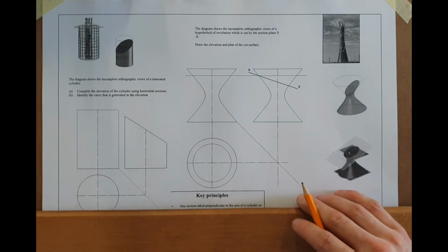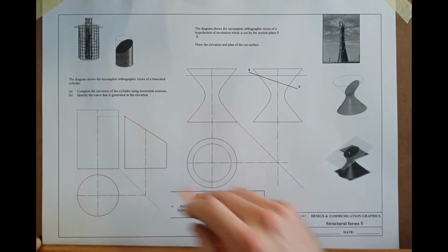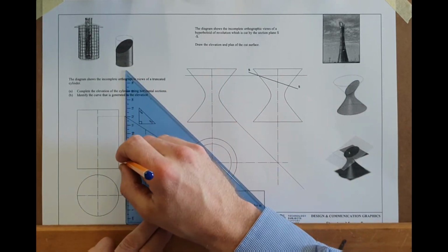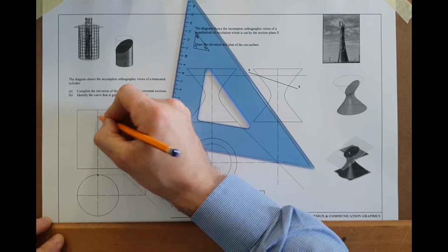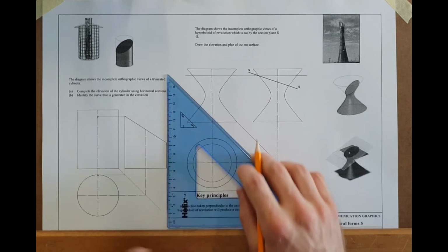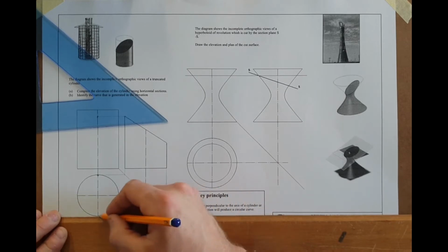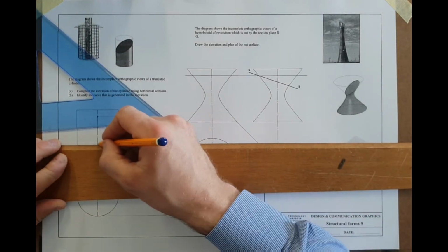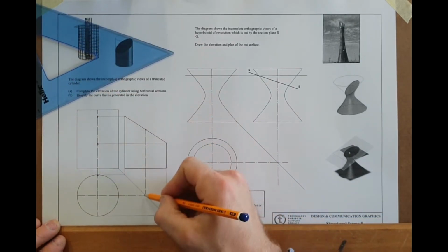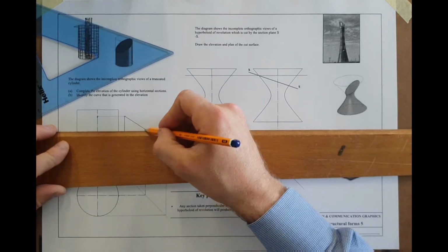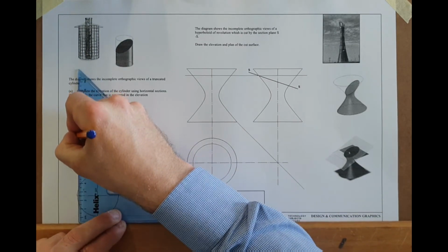Look, horizontal sections through a cylinder. Top point is here in the center. Now, I can reference the plan here, down to 45 and across. There's the highest point in the center. The lowest point is going to be here at the front of the object, so that's going to be across there. Highest point and lowest point identified. This one here is going to be the 2 midpoints left and right. So I get that much of my elevation right there.